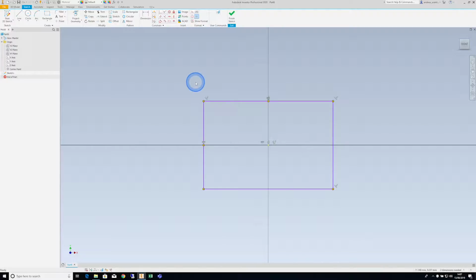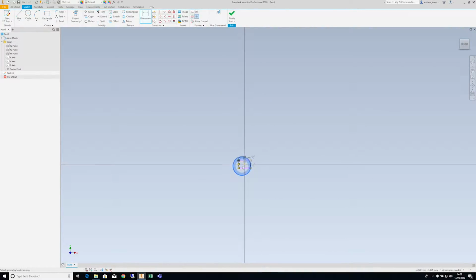Okay. Now the other thing we're going to do is put a couple of dimensions on there. So we snap to that line and we drag the dimension up here and we put in, let's say 20, hit return, and you see how these two lines now have gone black. They are now constrained. In other words, if I zoom right out, the software now knows that this is on this plane somewhere, and it knows that those two lines are parallel.